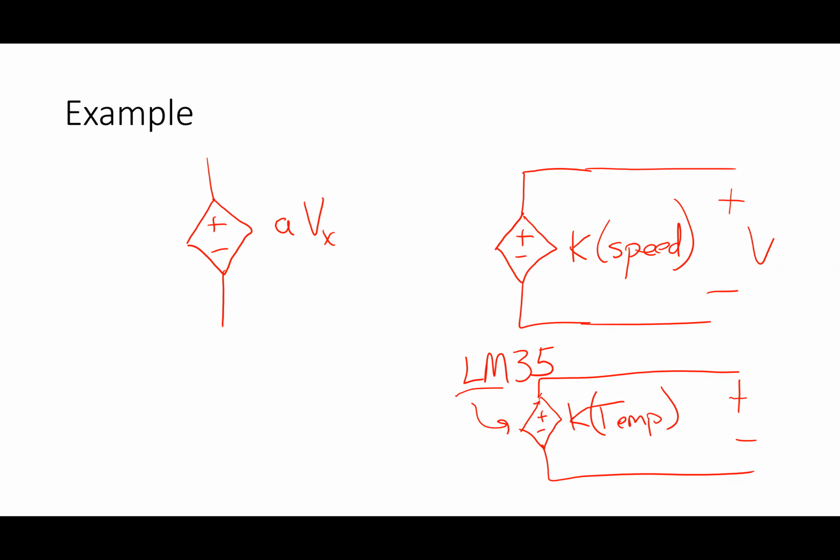So that relation is higher temperature, higher voltage? Yeah. There'd be what I call a gain, some multiplier here, that tells me if the temperature goes up by one degree, how much the voltage increases. That's just a coefficient. The manufacturer would specify that to you. It depends on the internals of that device, just like for a generator, it depends on the physics of the generator to tell you the relationship between the speed and the voltage.